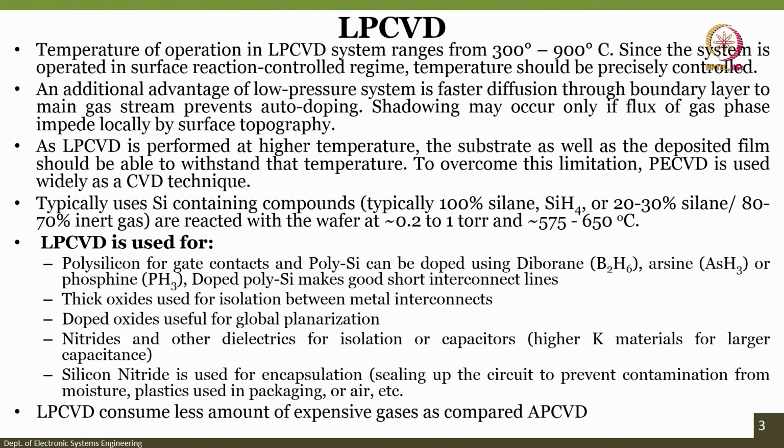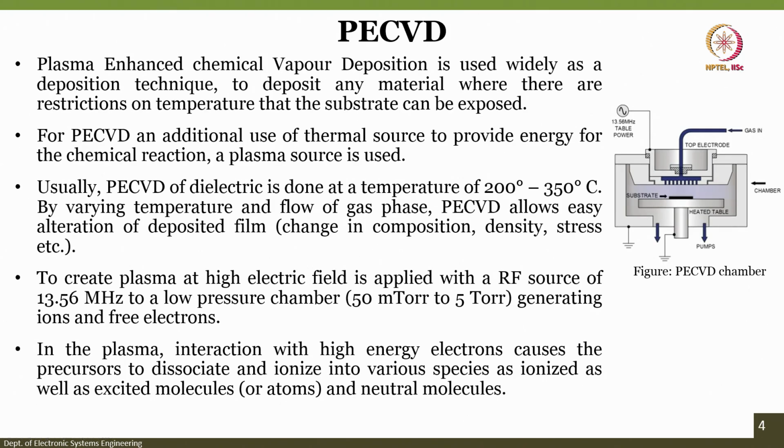Next one is silicon nitride, used for encapsulation, sealing up the circuit to prevent contamination from moisture, plastics used in packaging, or air, etc. Right. So, finally LPCVD consumes less amount of expensive gas compared to APCVD, right, we have seen earlier. Okay, great. So, let us go to the next one, which is the beautiful PECVD. Why did I say that? Let us understand.